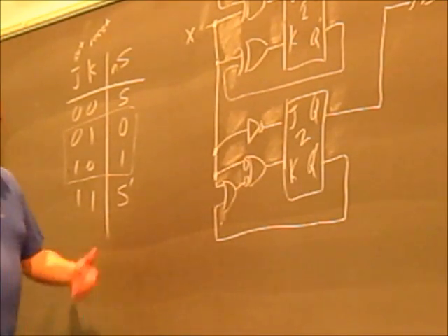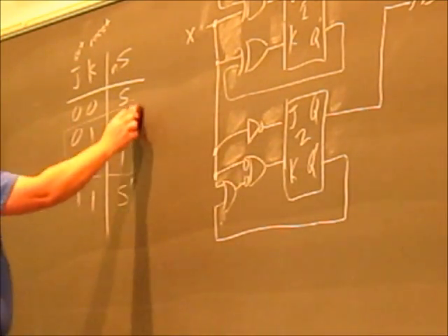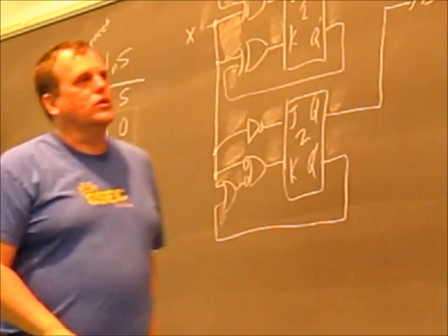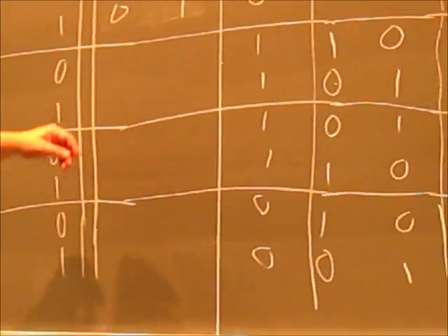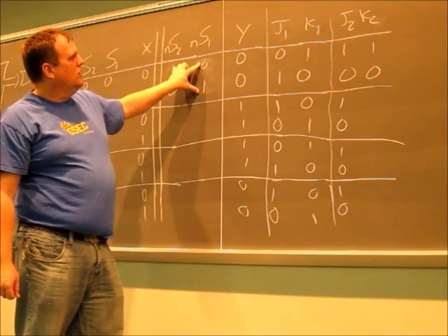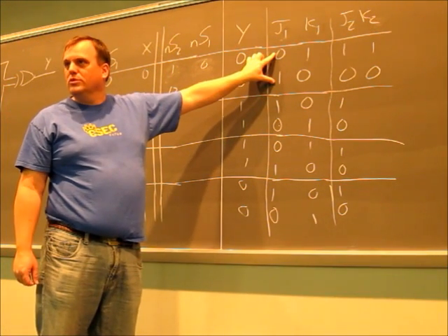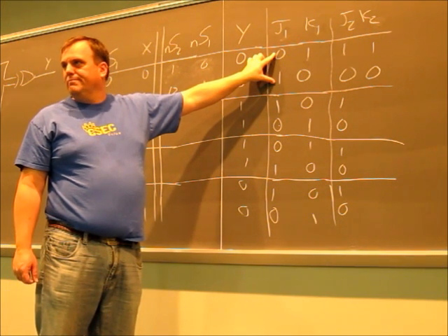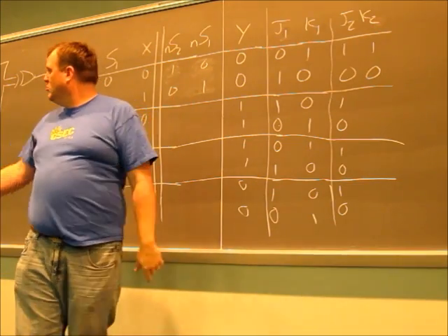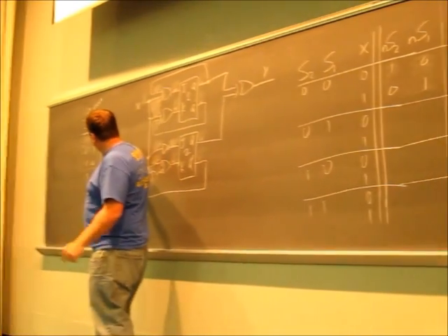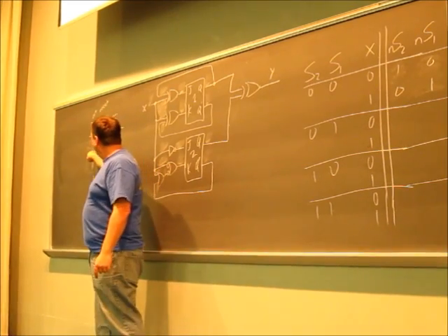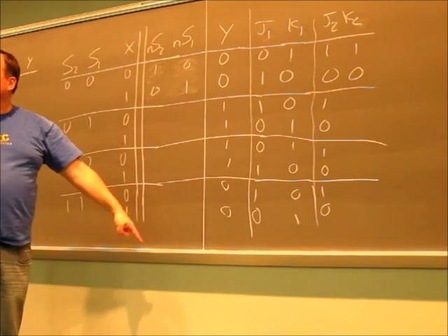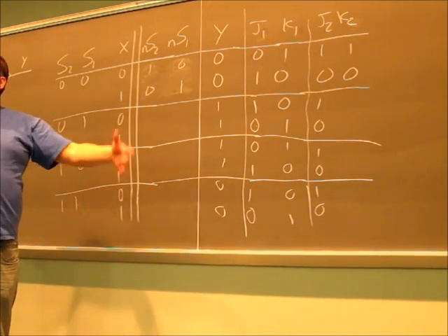Just an interesting note. And if you notice, for our state 1, it's identical to J1, because that's what we said. It's a D flip-flop on whatever's coming in J. Right? If you recognize that, D flip-flop, it either gets a 0 or a 1. That's exactly the same as J is. That just means I can copy J1 into my state 1. Do we all agree?